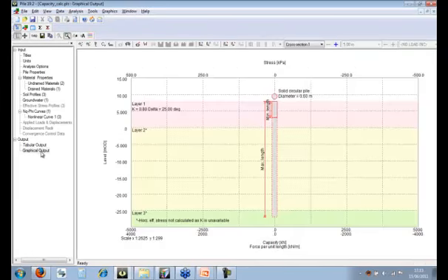So if we go straight to the graphical output, I'll start with the input parameters, and as you can see here, you've got a minimum length and a maximum length of the pile, and the range is shown with the dotted line. And right at the top, you can see a cross section of the pile. It's showing a 0.6 meter cross section here. But if I press the plus button, it goes up to 0.7 meters, and I'll show you how this affects the results just in a moment.